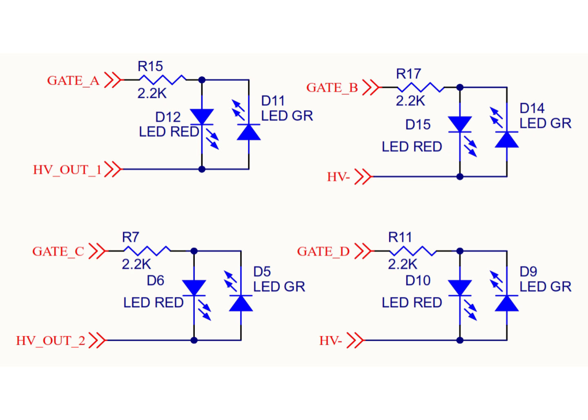Because the LED lights are referenced to the respective emitter, the indication accurately reflects the true gate-to-emitter voltage, not just the logic command. Overall, this LED indication scheme offers a simple, low-cost, and very effective diagnostic tool, allowing quick confirmation that all 4 IGBTs are switching correctly and in the intended sequence.